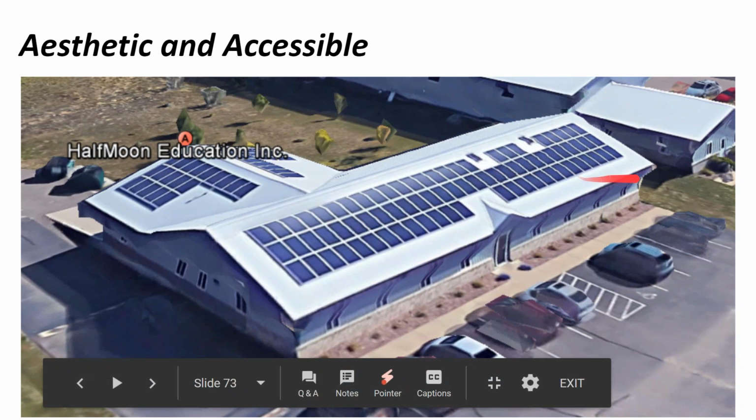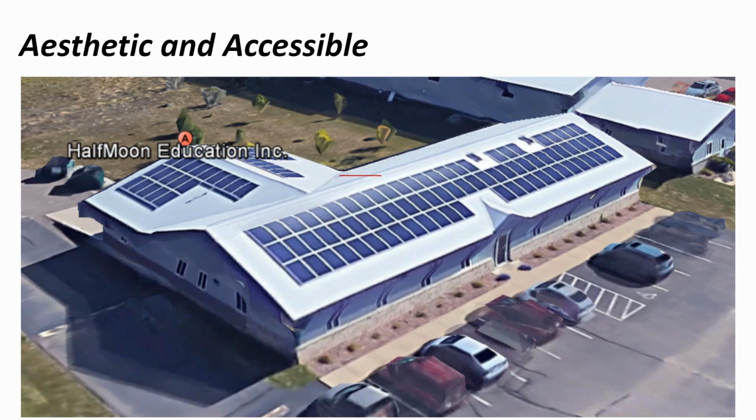But B, what we try and do now is, instead of assembling the whole thing on the rooftop, do as much on the ground pre-assembly as possible. So we'll build our rails and mount our electronics and attachment points all onto our rails as much as we can. Depending on what lift equipment we have, we'll do it all in one piece, or chunk it up into maybe 3 pieces, but do as much on the ground pre-assembly as possible to reduce the time spent on the roof itself.